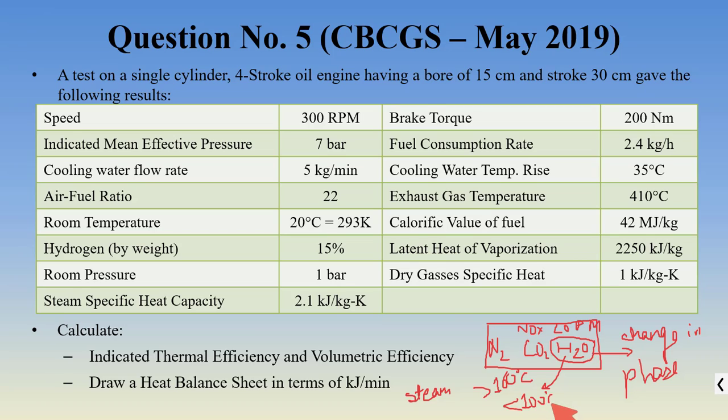So as soon as the temperature goes less than 100 degrees Celsius, what will happen? This steam will get converted into liquid water, right? And whenever any gas liquefies, there is some amount of heat rejected by that. That is equal to what? That is equal to the latent heat of vaporization, right? That is what they have given over here. I will come to it in a minute.